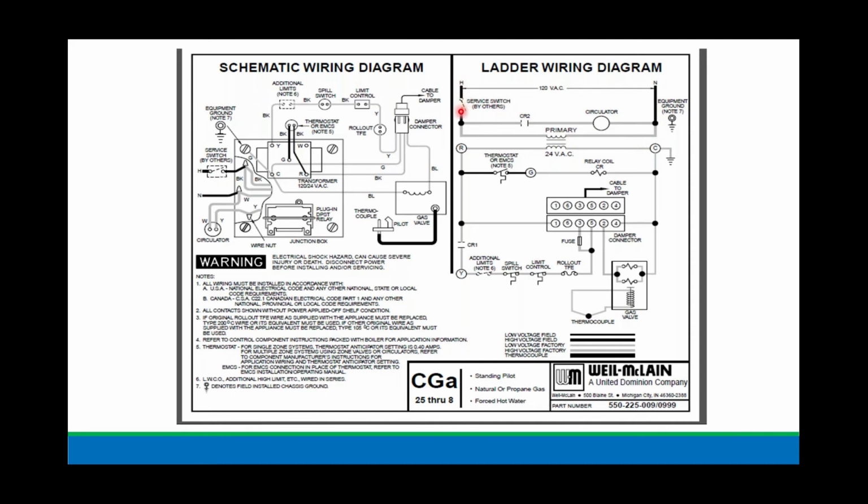And you can see on this rung there's a CR2 switch normally open and a circulator. Then we have our transformer. Here's our low voltage side. So here's my power. Let's look for our switch, which is our thermostat. And then we have a relay coil CR. That's my load, power switch and load. I complete that circuit. What happens to this CR relay coil once we energize it?